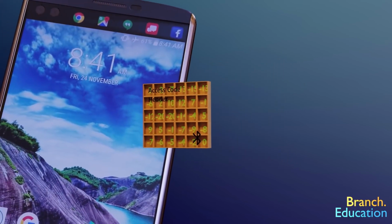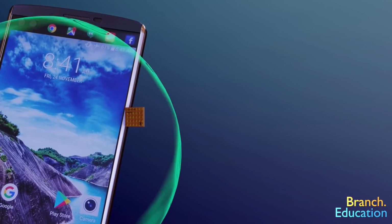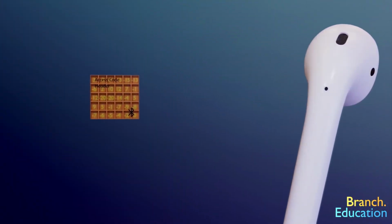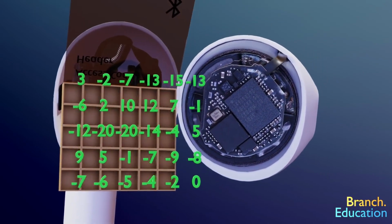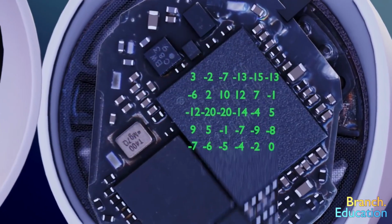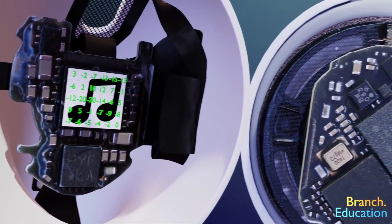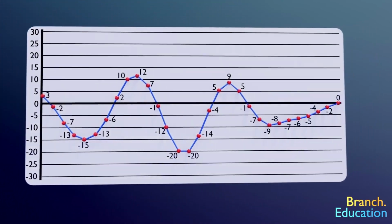Next, your smartphone converts these packets into electromagnetic waves or photons and sends the data to the earbuds over the Bluetooth connection. The earbuds receive the data and disassemble and decompress the packets back into long sets of values. These values are then sent to the audio codec, which converts the digital values into an analog electrical waveform.